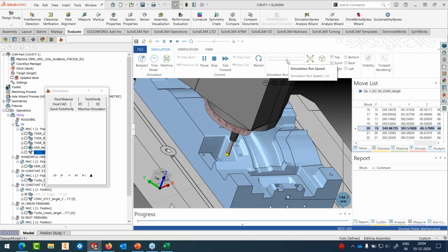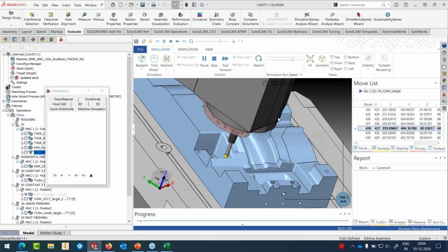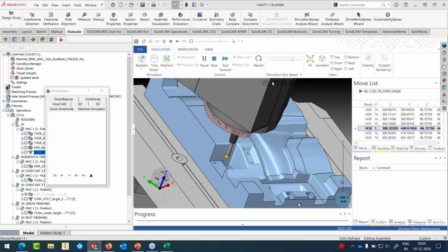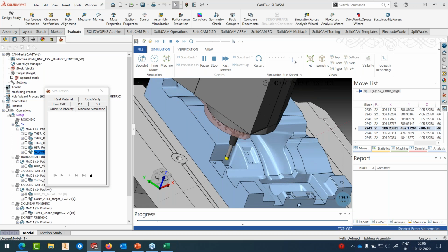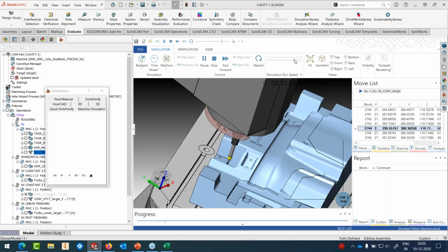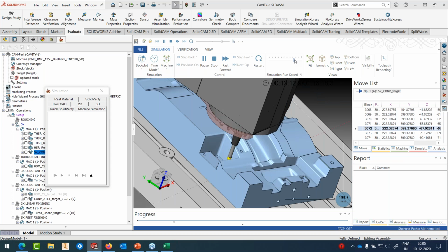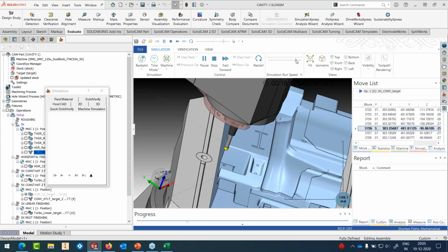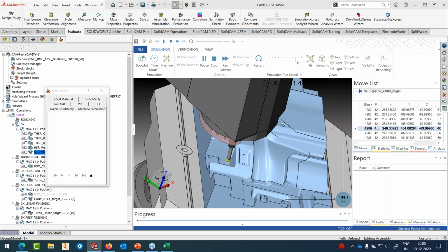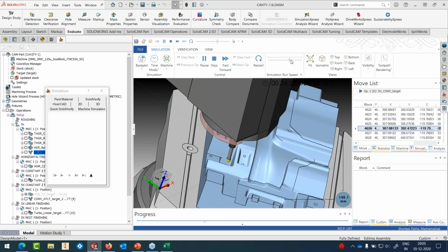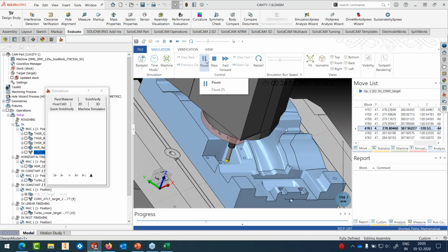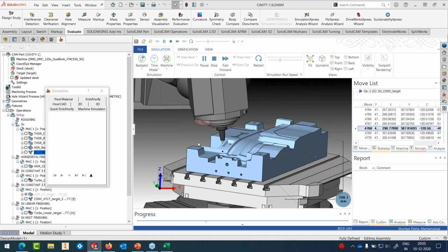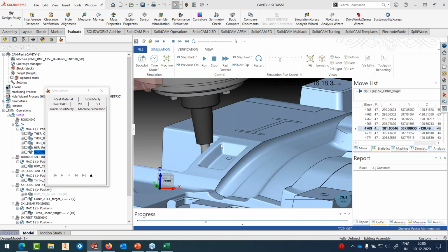And this is how my toolpath will run. So 3-axis. And as it goes down, I'll try and take you directly down below when it goes into the depth. It's already started moving, but I would like to stop at a particular point and show you. So when it comes close to the holder, you can see SolidCAM tilts this part.